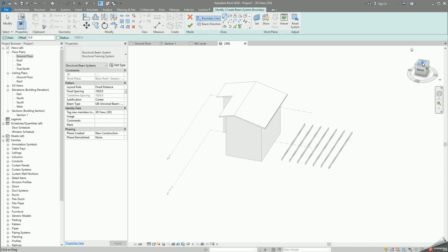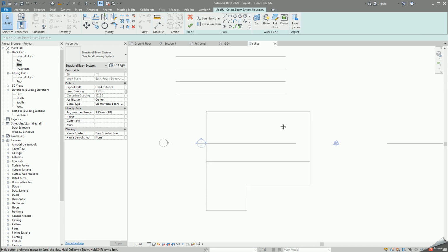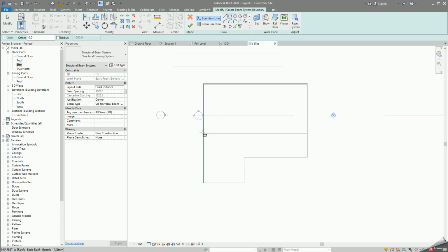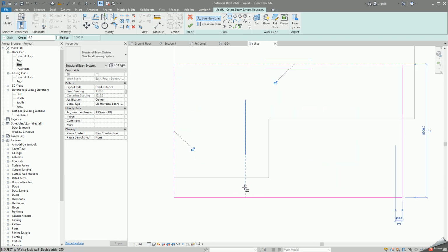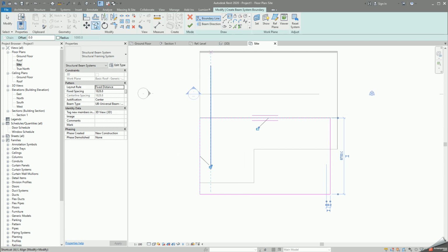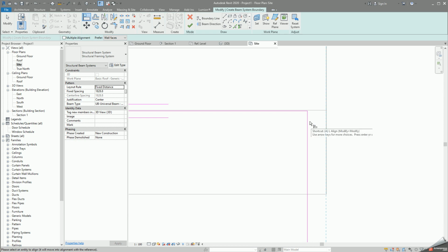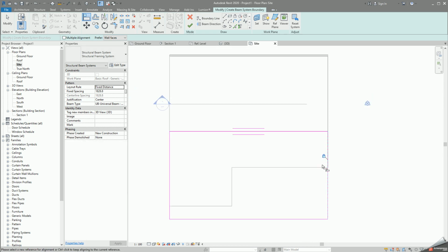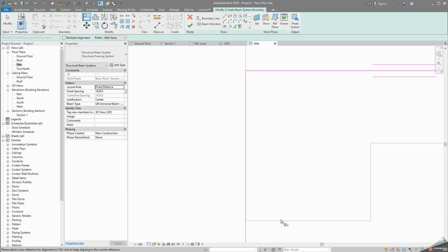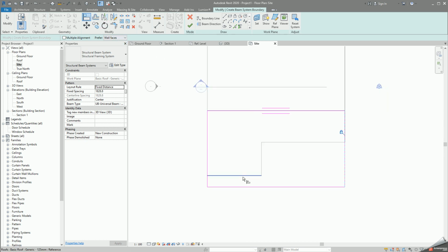And then you can either go to the top view, go into one of these side views like this. It makes no difference really. And then you can sort of start creating the size of the truss. So in this case, you can make it exactly the same size as the roof, or you can make it slightly larger or smaller, whatever your design dictates. So in this case, I'm going to make it like this. I can lock that in so it moves with the actual roof. So the align tool works really well this way. So I can select the roof itself and align that one to there and click on lock.